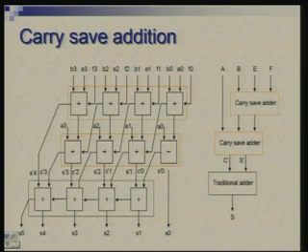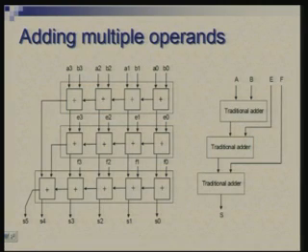Okay. So, let us compare the delays. In this case, what is the maximum delay? What is the longest path you can think of? Try from any input to go to any output. The longest path would be something which leads to this, and there are many ways, because any horizontal movement or any vertical movement, you could either go like that and like that.